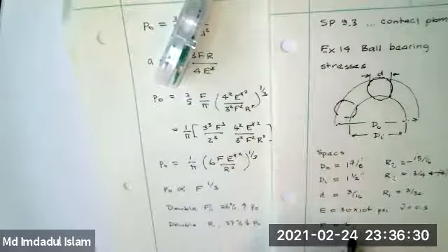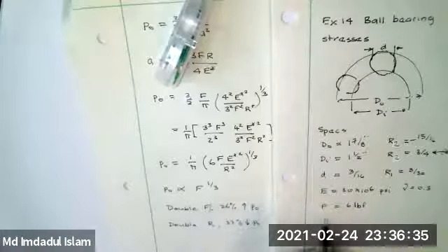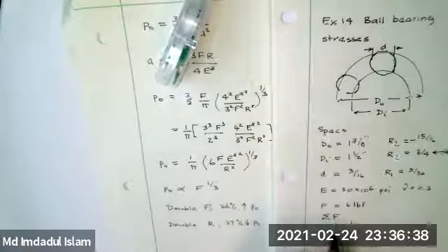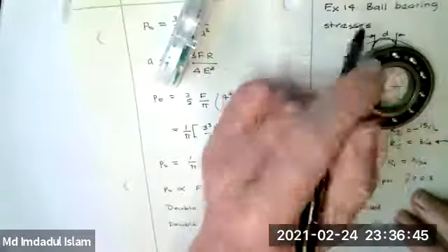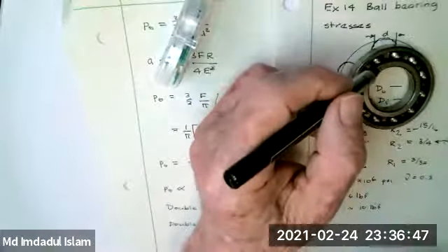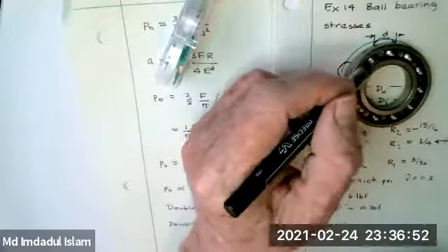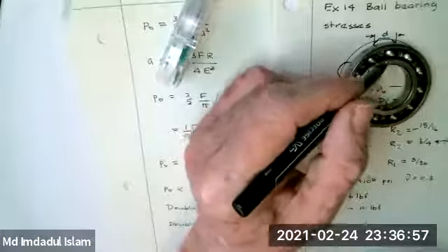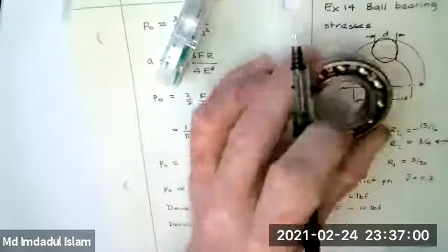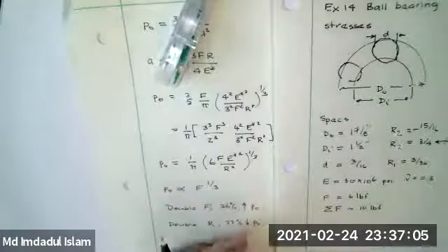And I'm going to say a ballpark figure of 6 pound force. I got that by looking at this thing and thinking the sum of the forces will be around 10 pounds. Where did that come from? You get 6 pounds from this. These two are well away from that, not like the roller bearing, they're not close. So they might only be a couple of pounds each. And these two will be basically zero. So that would give you about 10 pounds. And that would not be an unreasonable lateral load for a bearing like this. I'm not saying it is the rating, I don't have that, but that would not be an unreasonable number.